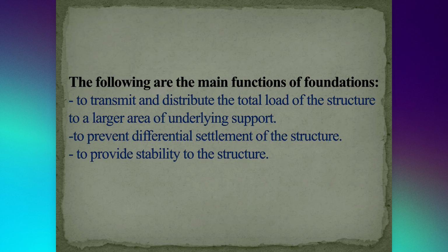The following are the main functions of foundations: to transmit and distribute the total load of the structure to a larger area of underlying support, to prevent differential settlement of the structure, to provide stability to the structure.